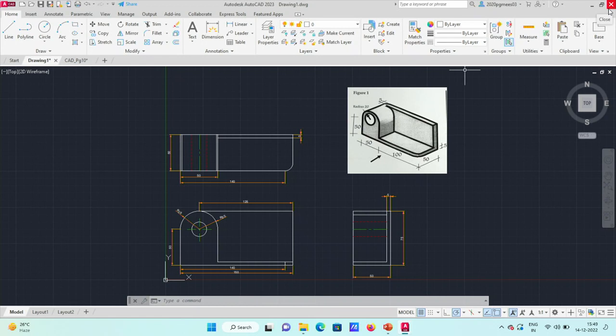If you are seeing this third angle projection and you have to draw the isometric view, how will you identify it as a curve? One thing, that should be the dotted one. We can do it like a dotted one. Like over here, we are asking why there is a thin line. That is to identify this is a curve. So listen. From the front view only, if this is a circle,